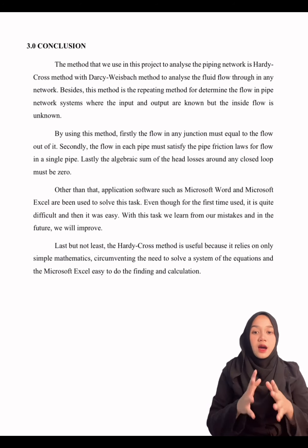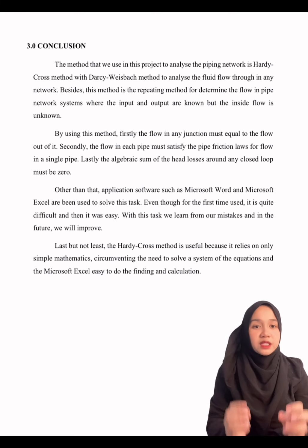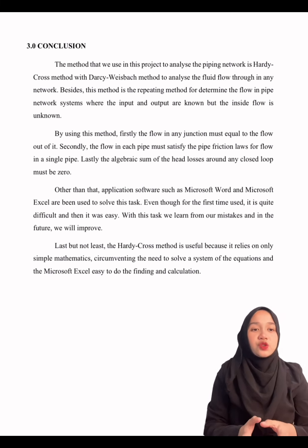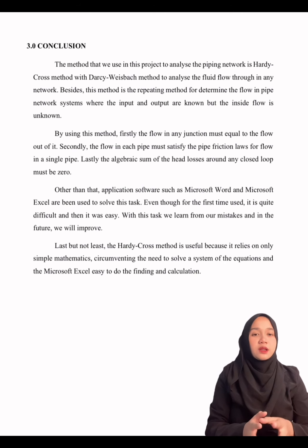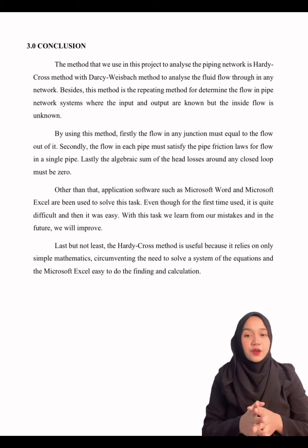Last but not least, the Hardy-Cross method is useful because it relies on only simple mathematics, circumventing the need to solve a system of equations, and Microsoft Excel makes the finding and calculation easy. Thank you from us.